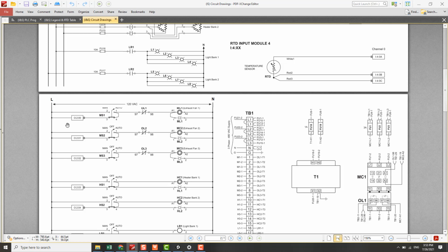So when we put the red probe of the multimeter at point 3, the current flow through here will be divided into two paths, or branch into two paths. When I say divide or branch, it means a parallel circuit. So one side to the load, the other side parallel to the multimeter.